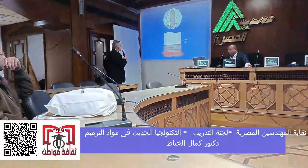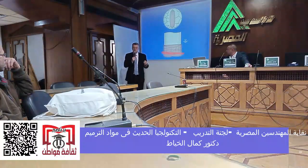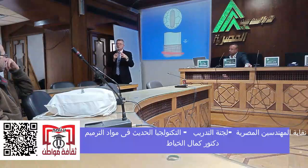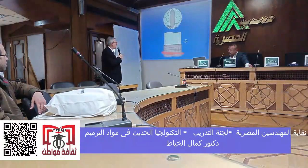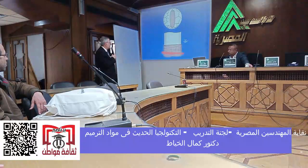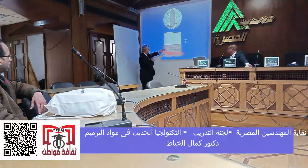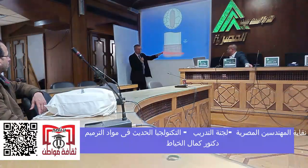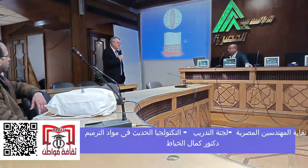So the cracks that you see are vertical, horizontal, radial, and they determine that those are dormant cracks. That means if you inject them, they're not going to continue moving. So you can inject them. And the reason they repair it is to keep it integrated so it doesn't disintegrate. And also you don't want a block or big concrete in the shipping lanes. There's a lot of boating and shipping and leisure boats.